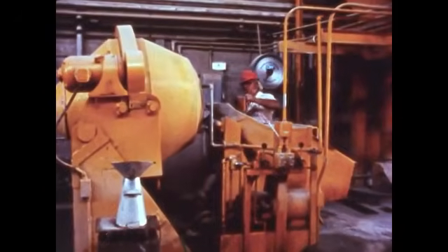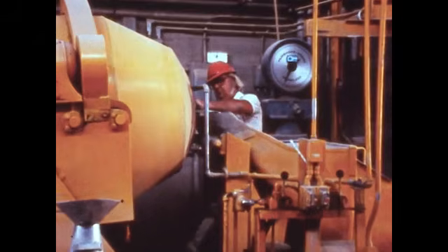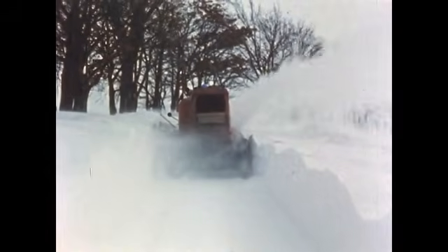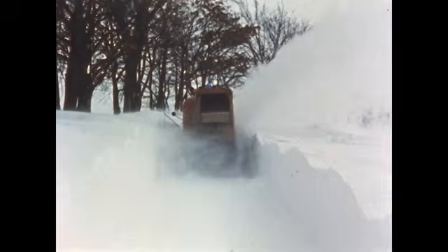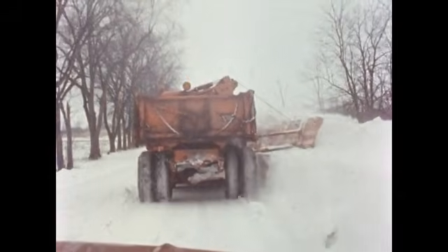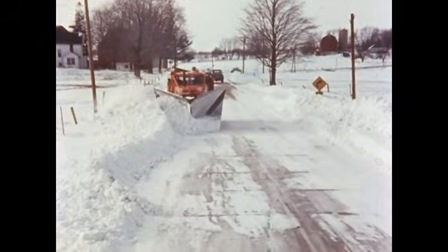The use of a chemical agent, which may be ground with the cement or added at the mixer to intentionally entrain air in the mix, develops millions of tiny air bubbles in each cubic foot of concrete. These act in the same manner as ball bearings and make it more workable. The bubbles also provide minute pockets for the expansion of trapped water during freezes, easing pressure on the concrete and improving its durability and resistance to surface scaling.